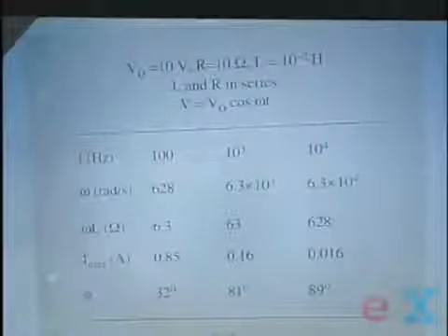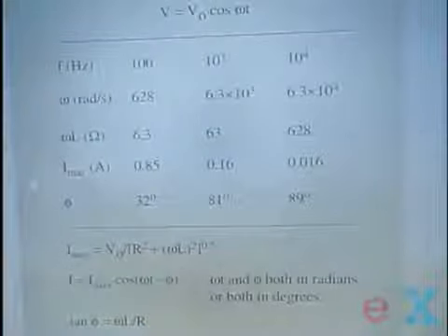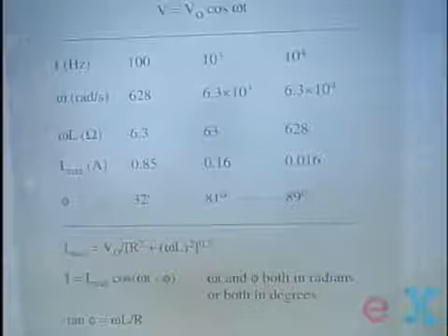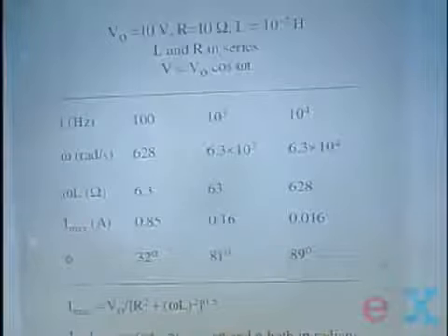And so the current that is going to run, at least this is the maximum current, is this value, which we also saw here on the blackboard, that current at high frequency is enormously reduced. It's 50 times lower than this current at low frequency, even though they have the same value for V0. And then you see here the phase angles.